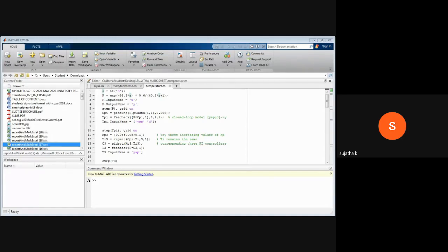Then you want a process, right? You want a process and you want an on-off control. For getting the process, you click on Continuous. When you click Continuous, you have the transfer function block here. Drag this transfer function block and place it here. My transfer function will be 1 divided by 1 plus 5s.